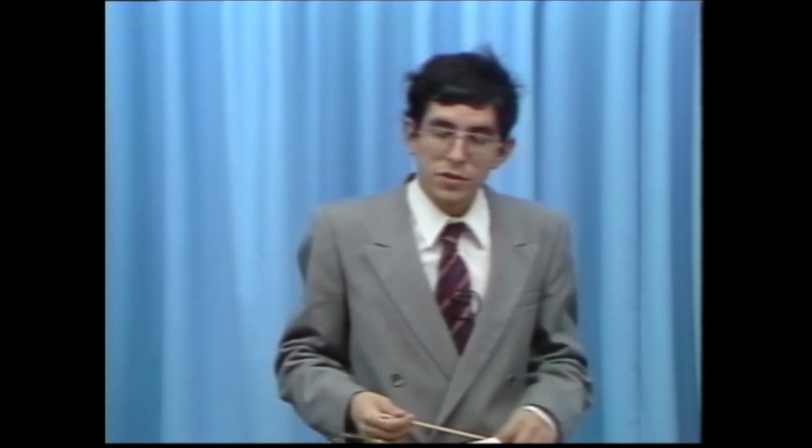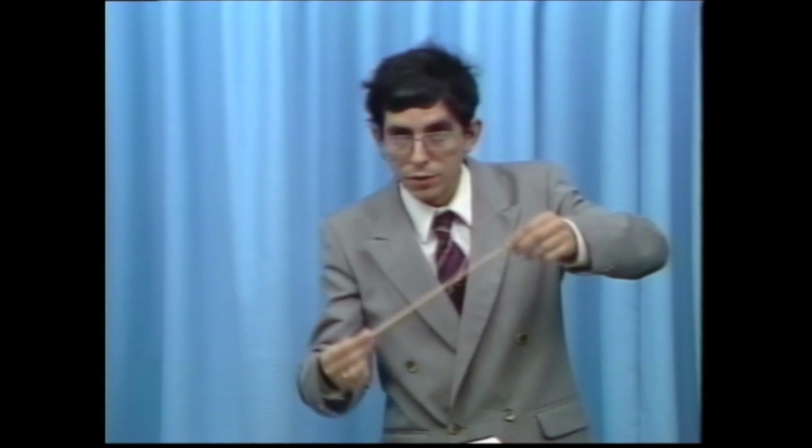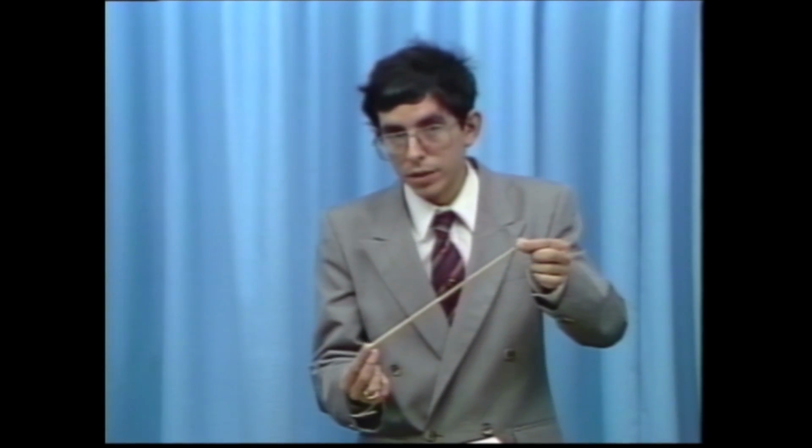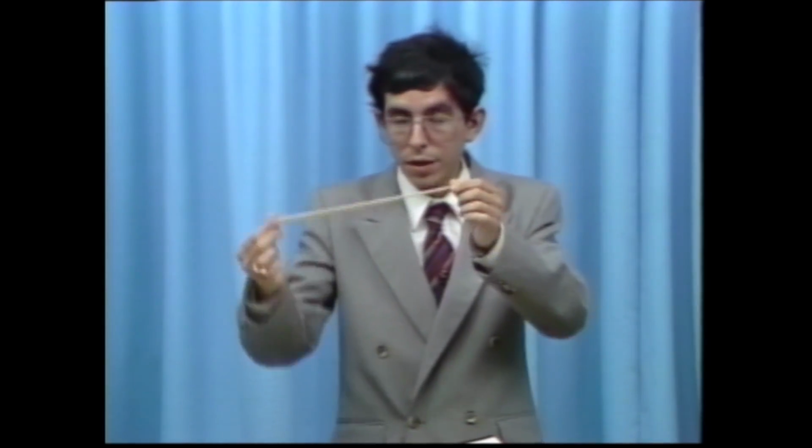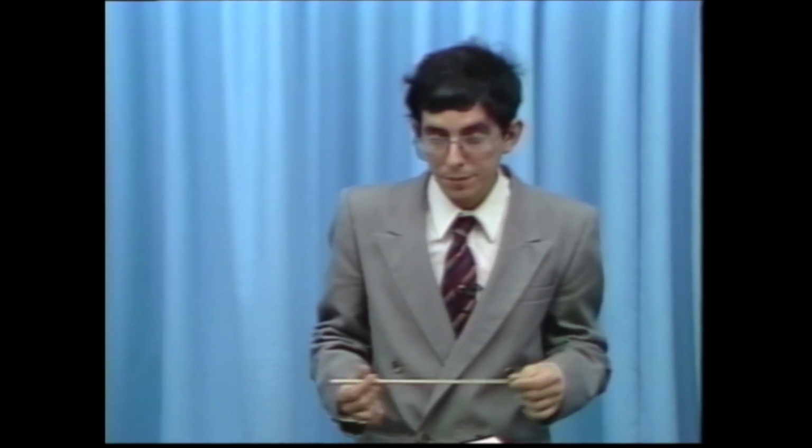For now, the suspicion is that something like NAS would have to be designed to accommodate that changing shock position. Whereas you might actually design it so that at lower Mach numbers, the shock is sitting far below the cowl. And then as you increase the Mach number, the shock moves up towards the cowl. And then eventually you get some crossover point and the shock gets swallowed into the cowl.